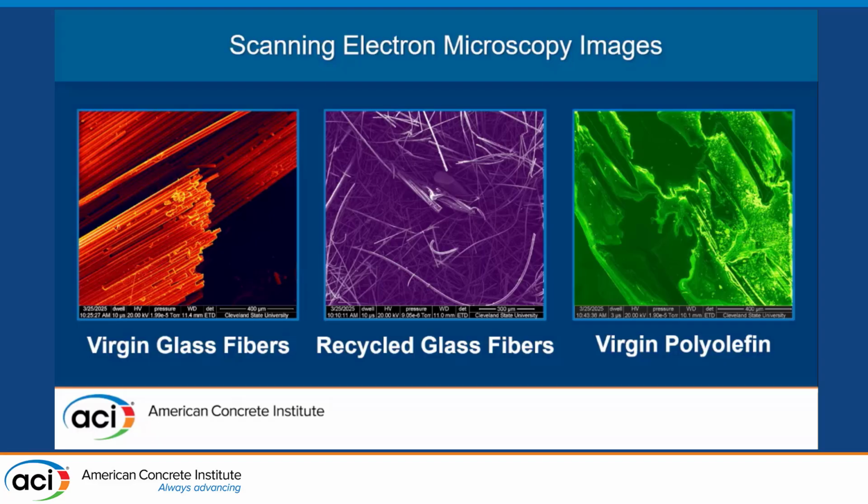And with the virgin polyfin, something interesting is it has a deformed pattern like rebar, so it can better grip onto the concrete matrix. That's later going to allow pull-out behavior instead of failure by rupture. And it's going to be one continuous fiber, compared to the other ones, which are a mixture of them.